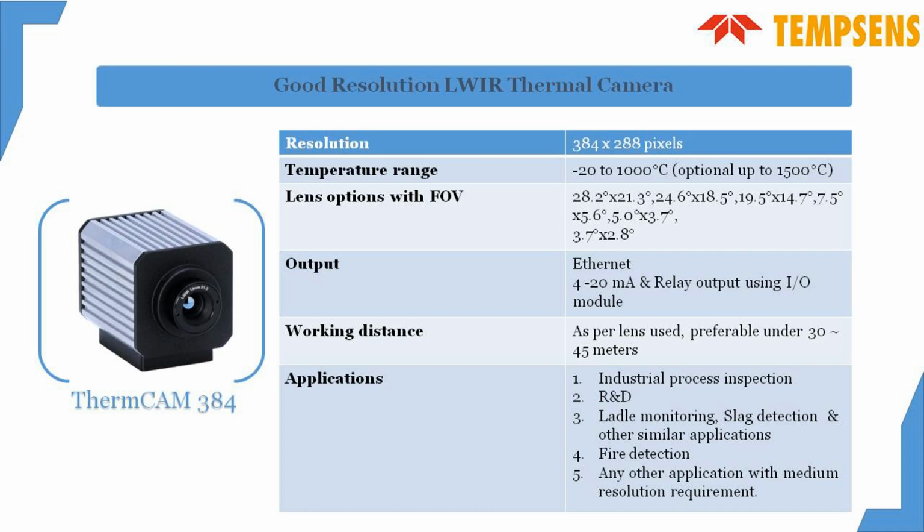Output Ethernet, 4 to 20 milliampere and relay output using input output module. Working distance as per lens used, preferably under 30 to 45 meters. Applications: wide industrial process inspection, R&D, ladle monitoring, slag detection and other similar applications. Fire detection, any other application with medium resolution requirement.